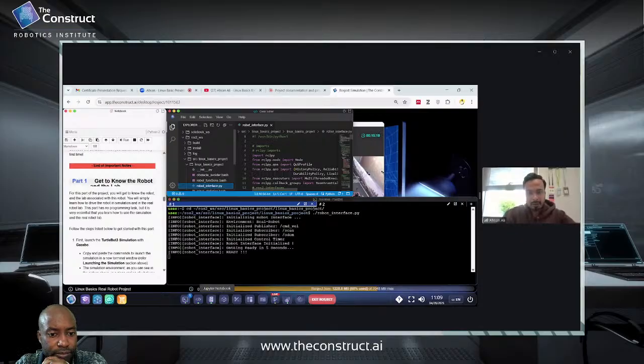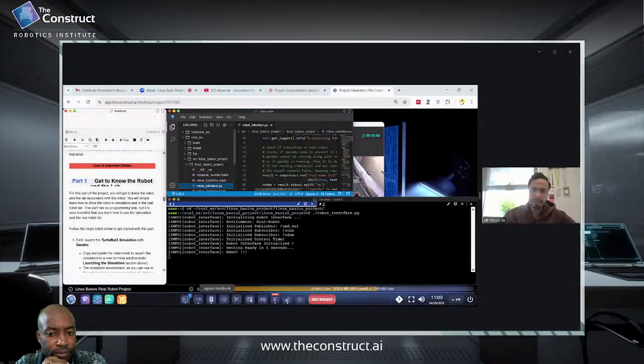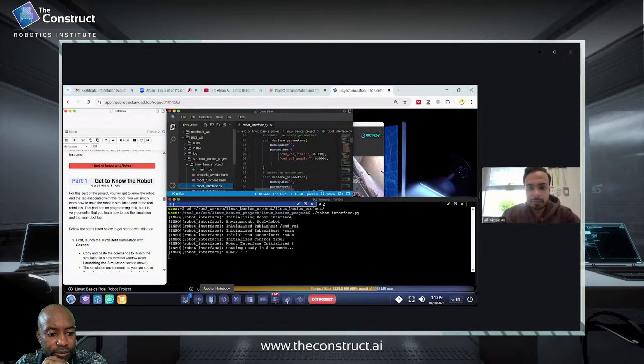It imports the nodes and everything, and then we have the sensor messages from IMU, which we have ignored. There is the robot interface node, which is responsible for initializing the interface and setting up the environment. You can see that it scans the angle minimum, maximum, the increments, the range of the lidar which is mounted, the position of the robot, and other stuff.